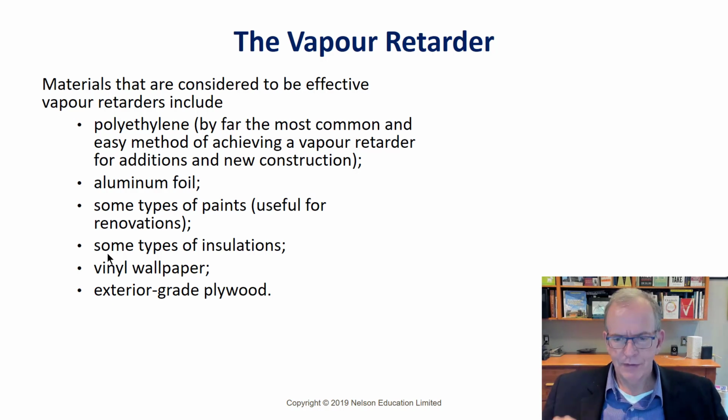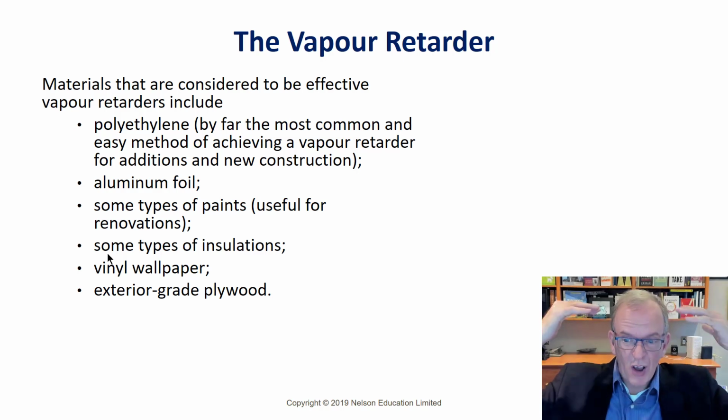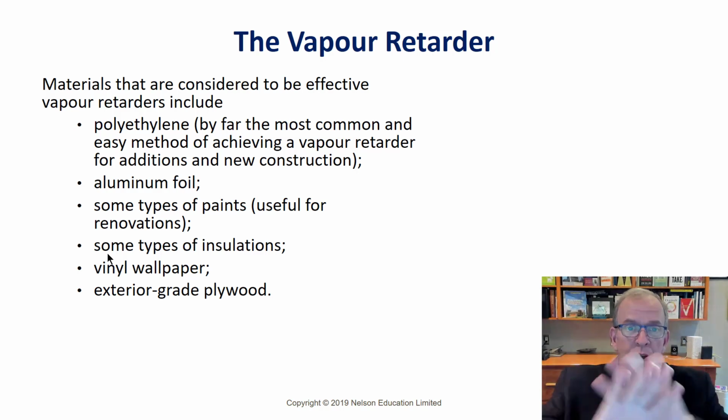They had grass and stuff, and they had sprinklers, and the sprinklers were hitting the side of the house or the motel, and the sun was out while it was hitting them. So they had basically sun-driven moisture and heat-driven moisture, because you got the sun against the wall, it's hot, and you got this spray of water going against it.